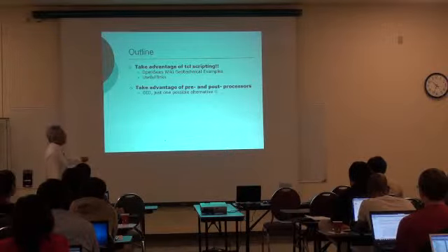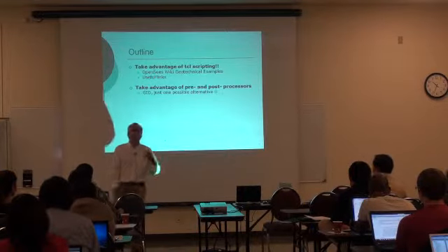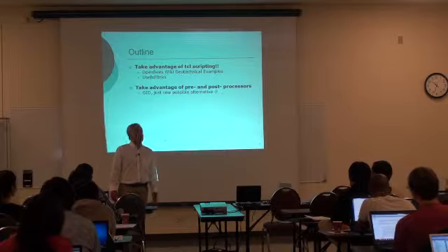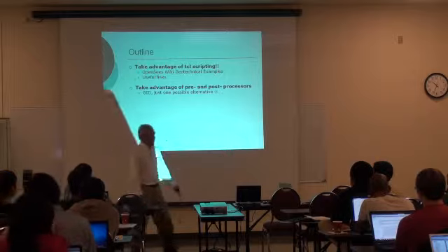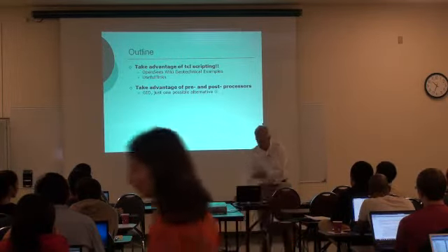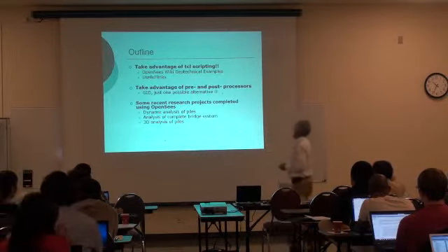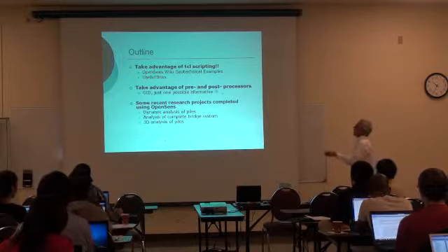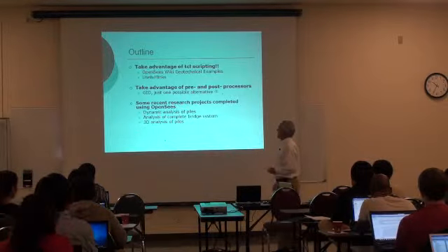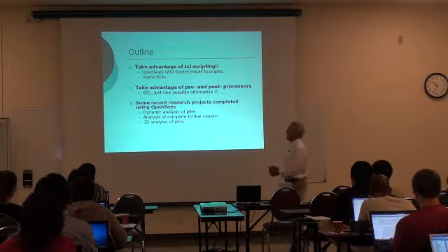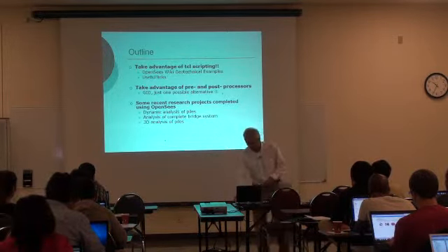I have been using what is called GiD, which is a pre and post processor that was developed at the CIMNE. CIMNE is the International Center for Numerical Methods in Barcelona, and it's just one possible alternative. There are many other alternatives, and I will mention this one because I've been using it. It's not public domain, but it's not that expensive. And I want to talk a little bit about some recent research projects that I developed using these things and GiD. In particular, I want to talk about the dynamic analysis of piles, analysis of a complete bridge system, and also the 3D analysis of piles that we are doing.